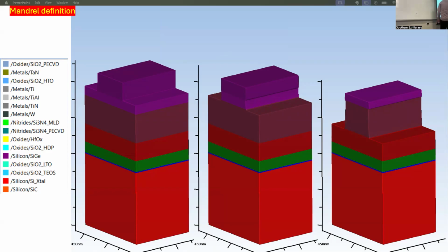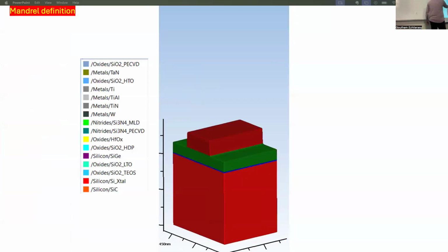So you use the mask to pattern this resist, and then you use this resist to pattern your different layers. First you pattern your Si ARC, and then you use your Si ARC to pattern your ODL, your planarization layer. Remember, when you do this patterning, you do one step at a time. You use one to pattern the other, and the other, and so on. And then finally, you see the pattern is transferred to the poly. So this poly is now the mandrel, okay?